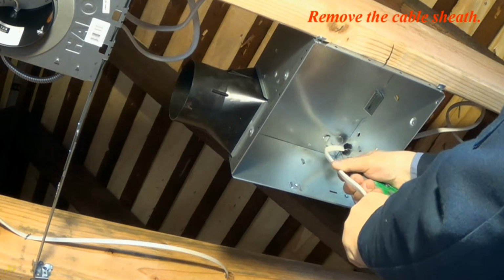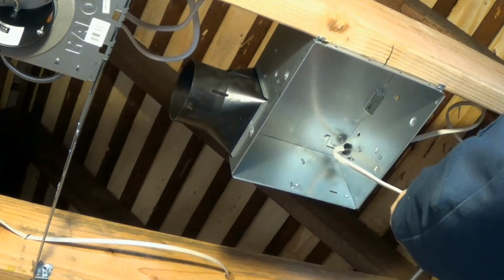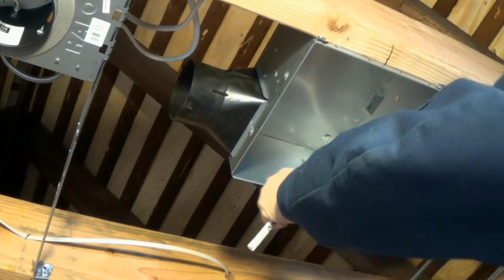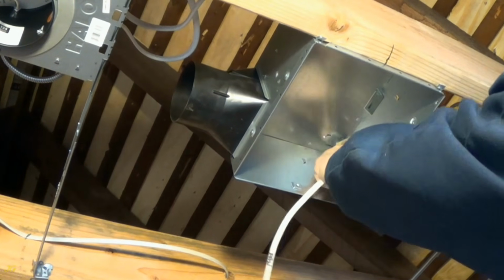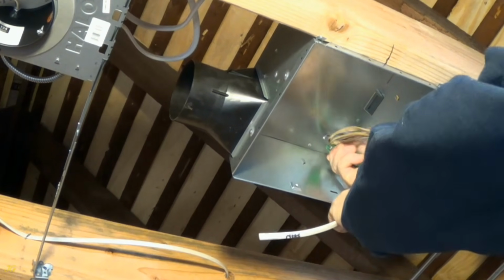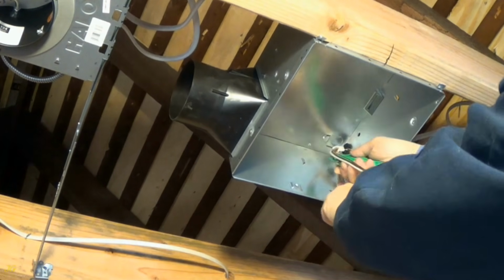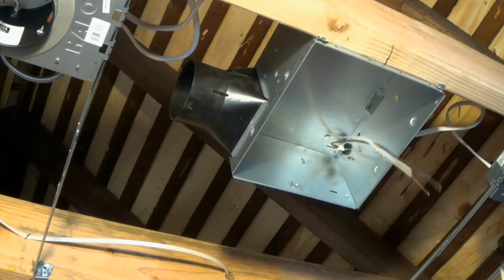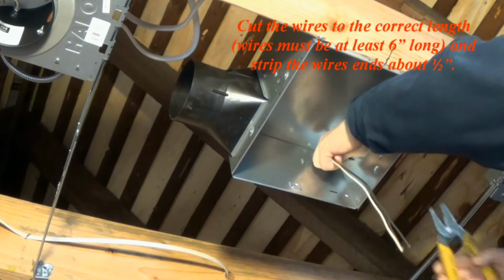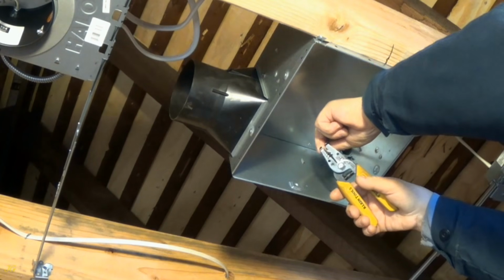Remove the cable sheath. Cut the wires to the correct length. Wires must be at least 6 inches long, and strip the wire ends about 1/2 inch.